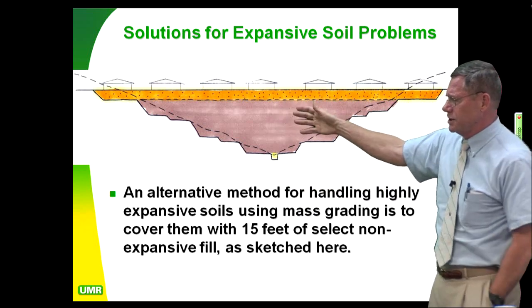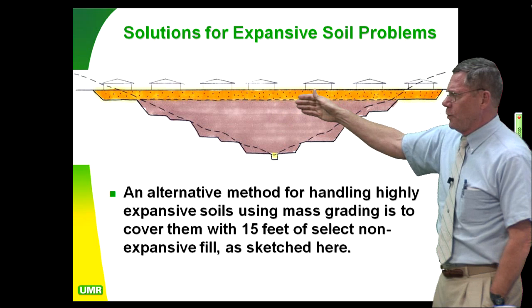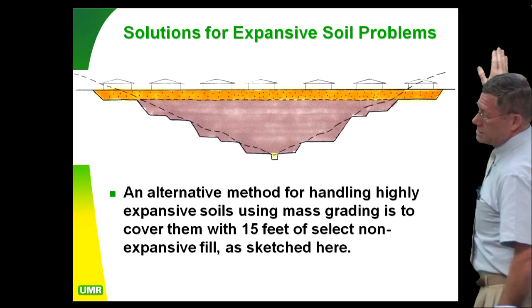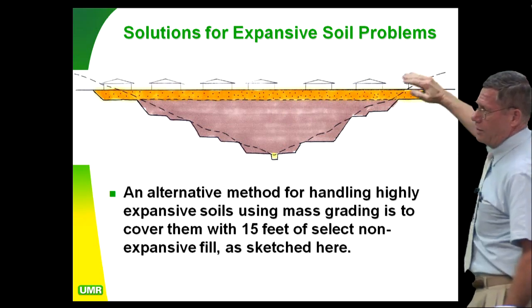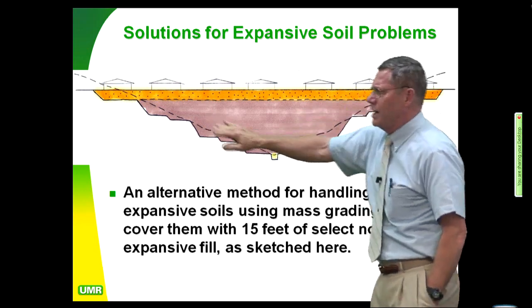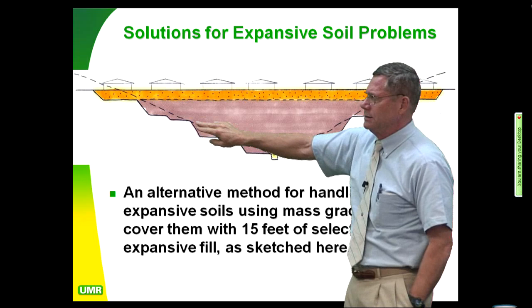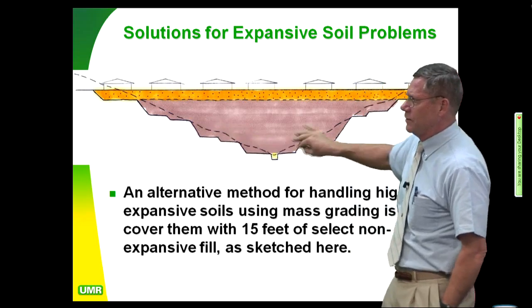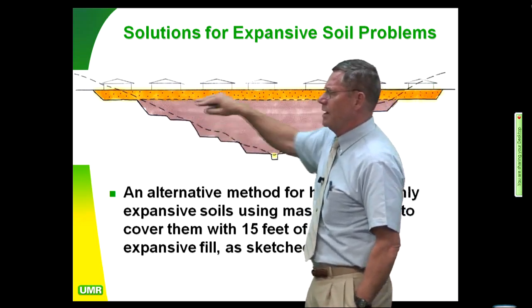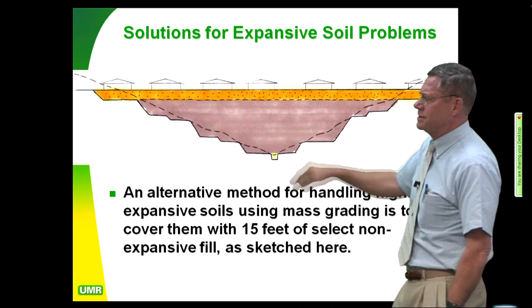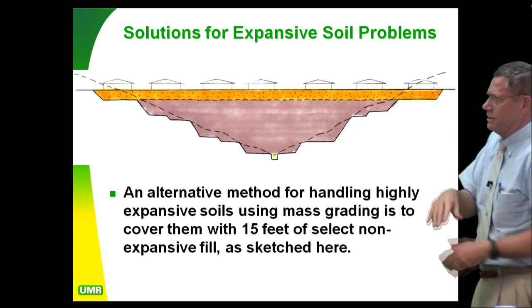Now, this kind of solution can work well for you if you're taking the soil type material out, hogging it out first, and filling in the valley bottoms with that. But you have to over excavate the bad materials out of here, the clays that are down here. You have to over excavate those out, and then roll them back into this thing so you don't cause consolidation of those materials.